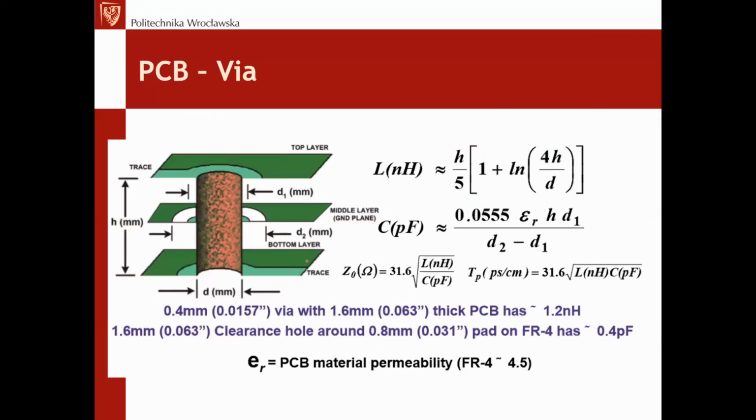Okay, now we talked about the via. And now a few remarks about the vias, about the tracks, about the electrical properties of those elements. In case of the via, we mentioned their importance. So we have a trace, and the trace gets to some layer, because it can be between the layers, between top and bottom, but it can be as well between the internal layers.